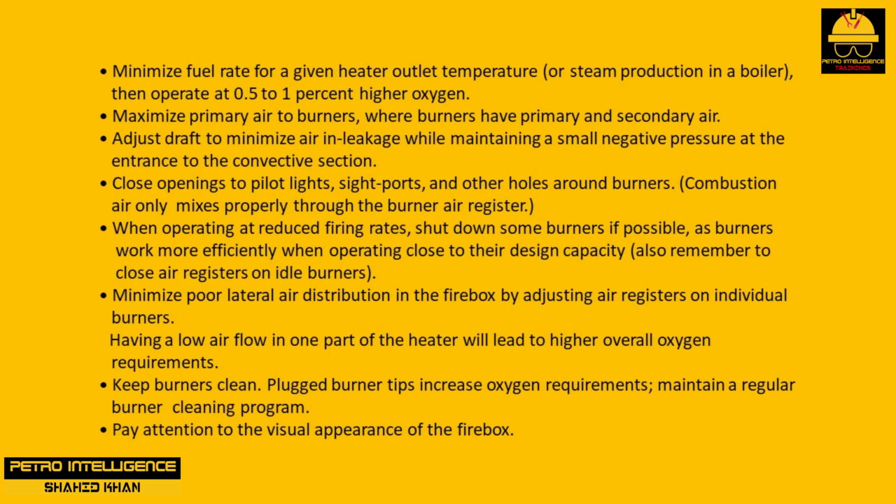Combustion air only mixes properly through the burner air register. When operating at reduced firing rates, shut down some burners if possible, as burners work more efficiently when operating close to their design capacity. Also remember to close air registers on idle burners.